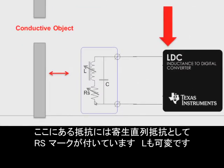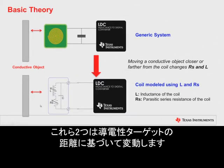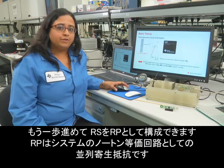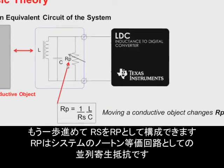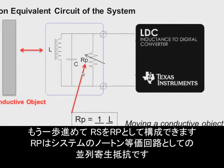The resistor here is marked RS as a parasitic series resistance, and the L is also variable. These two vary based on how close or far away you're moving your conductive target. To go a step further, you could model the RS as RP, RP being a parallel parasitic resistance as a Norton equivalent circuit of the system.